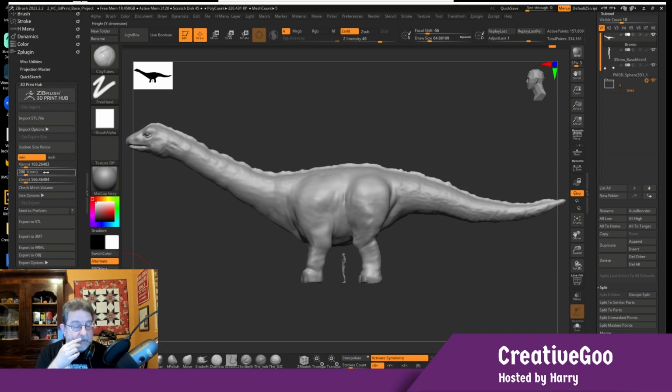So he's supposed to be 200 millimeters long. But that means in the X direction or the Z direction, he's going to be 566 millimeters long. That's 56 centimeters. Well, if your printer can't print 56 centimeters, he's not printable. Even though he's a solid piece, he's super deep.